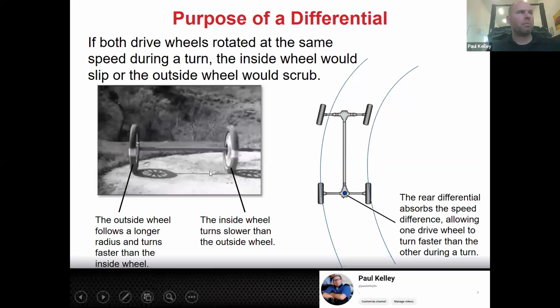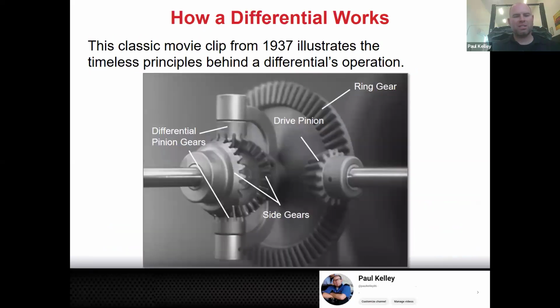You guys even notice this is from that video that you did. However, so is this one. So the way that we did that, if you'll recall, our pinion was coming in like this. The pinion is driving the ring gear. The ring gear is turning this arm and all this assembly. Most of the time they'll call this part the center section, but Toyota actually calls this the case. So the ring gear bolts to the case, and all these little pinion gears and side gears also, in a roundabout way, go to the case.